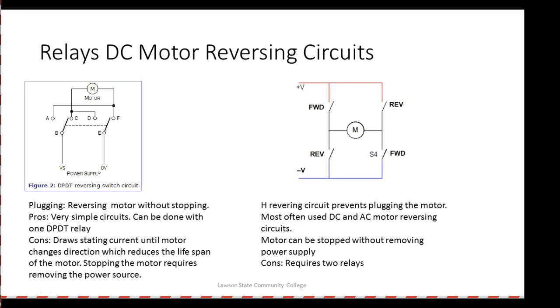Anybody have ceiling fans at their house? You ever reverse the direction and listen to that motor without it stopping? What does it do? Because it's pulling tons of current trying to reverse it, right? Understand? So normally what we like to do is have a method of removing voltage from the motor altogether. So I could come up here and add another relay down here that cuts off the power when I try to reverse it, but that's a bunch of trouble.